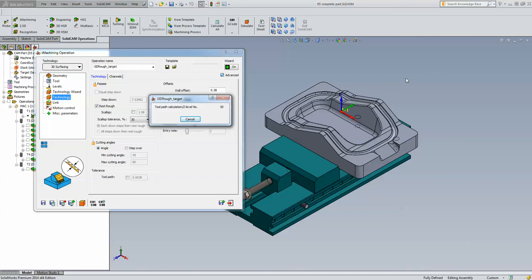Now, the advantage of using iMachining 3D is that it uses the actual iMachining toolpath to get the spin rates and feed rates up to really high speeds, and also deep cuts, making it very efficient. The toolpath runs without any vibration of the part, removing your material very quickly.